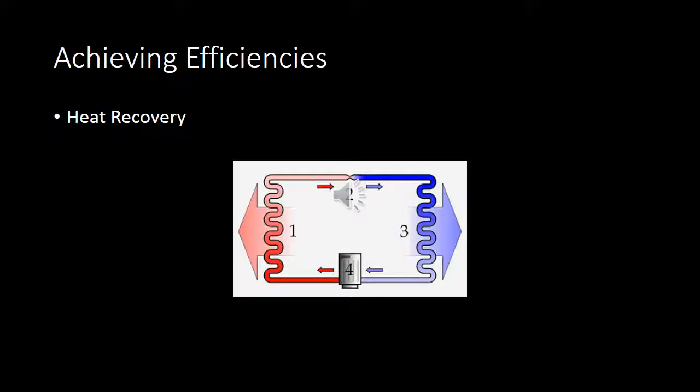Heat recovery. More than 85% of the electrical energy used by an industrial air compressor is converted into heat. In many cases, a heat recovery unit can recover 50 to 90% of the available thermal energy for space heating, industrial process heating, water heating, make-up air heating, boiler make-up water preheating, industrial drying, industrial cleaning processes, heat pumps, laundries, or preheating aspirated air for oil burners.